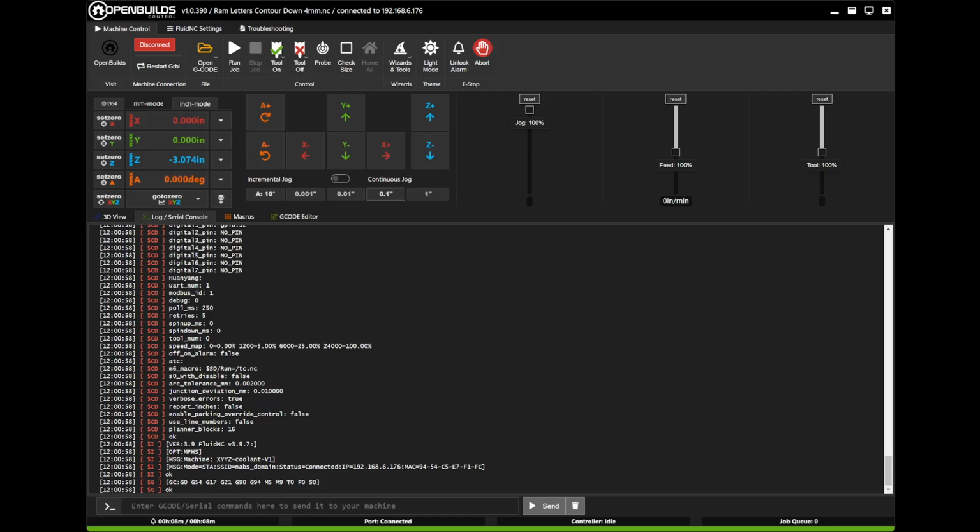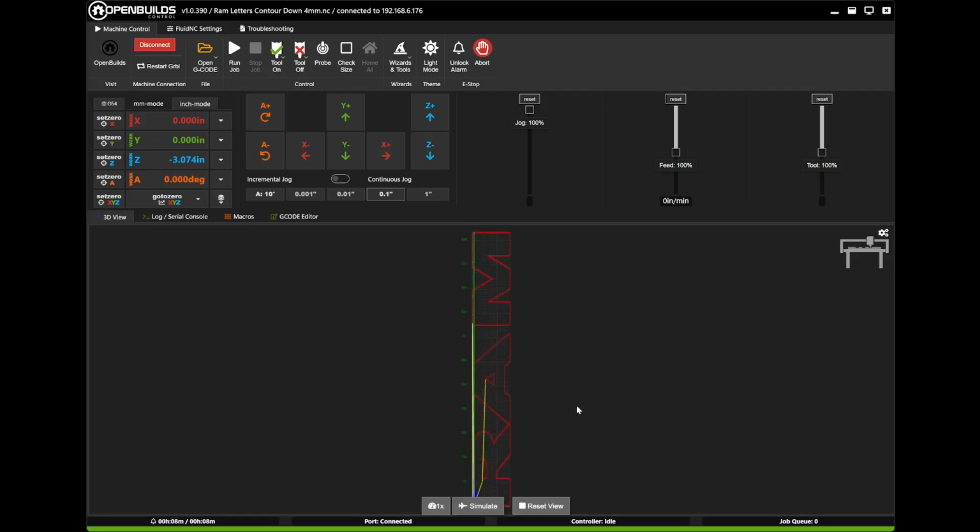And the great thing about this program is the ability to edit G code and see what's going on, plus the pro features. So I'm going to go over some of the things here. I have an actual G code loaded. So if I go to 3D view, you can see here, I got a 3D view that I can pan around, see where the machine is. I can tell the machine right now it isn't home to the workpiece. It shows me how many cuts it's going to do, how many times it's going to go around the outside, or similar. It does a simulation of the cut.